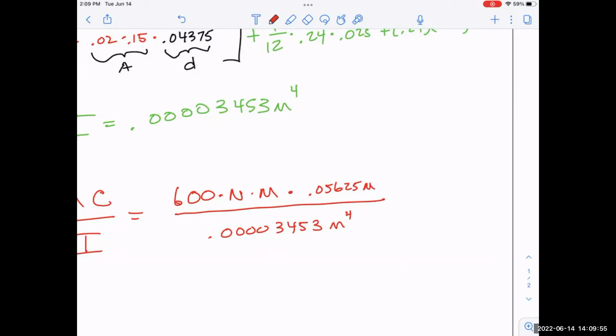Now, if you had it in millimeters down there, it's not wrong. You would just have some wonky unit, newton per square meter or millimeter to the fourth, and nobody would know what it meant. And of course, if you went to a table to look it up, will this material do it? That's not going to help, right? So it's going to be measured in pascals, just like our system is measured in PSI. It's got to be pounds per square inch or your table's not going to speak the language. So it actually was good that we had such a crazy number, but it's so tiny.